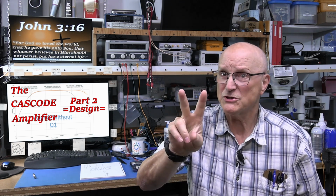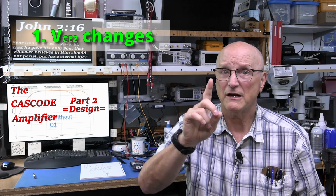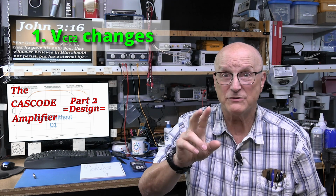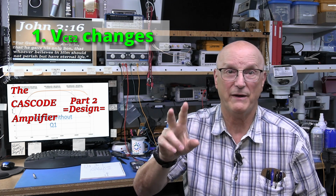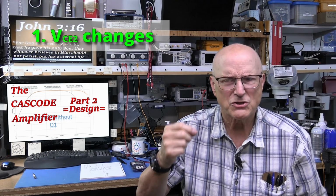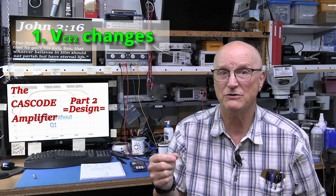But two things would change in the circuit if I do just this. First, the collector-emitter voltage of Q2 would change. Now, this would increase the amount of reverse bias in the base collector junction, reducing the base collector capacitance. So, we have to make sure that we maintain the same collector-emitter voltage on Q2.